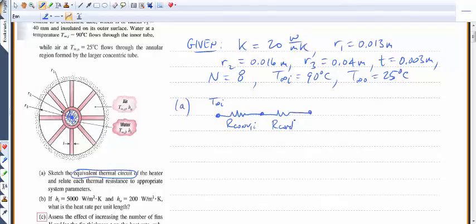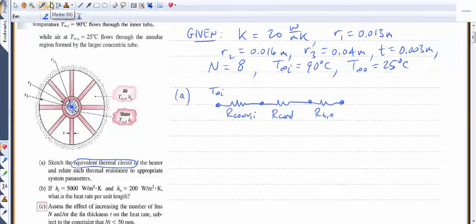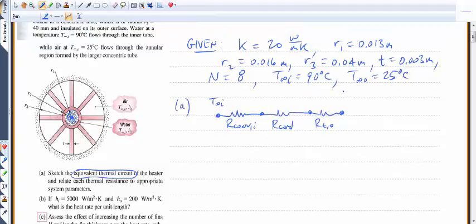And then as it reaches the outside of that inner tube wall, then the heat is going to go from this outside of the wall to the air through two means, either directly through convection at that surface of the outside wall, or through the fins. So with that, we have to then recognize that this is a fin array, so we're going to use the overall fin array resistance, R_t,o. And then, of course, this reaches to the air, and the air is at T infinity O.